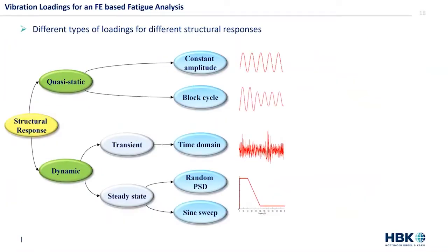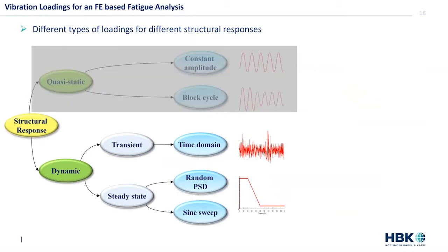So in terms of the different loading types, first of all, often the FEA analysis is done in the time domain, and people have time domain in mind. When we do measurements, it's all time domain. We saw that the standards mention PSDs, and shakers typically expect PSD specifications to drive a test. So depending on the sort of structural response, you may choose one or the other. Here we're interested in the dynamic structural response, like I think I mentioned, the resonances and so on. So it's very dynamic, so we'll go for the dynamic route there.